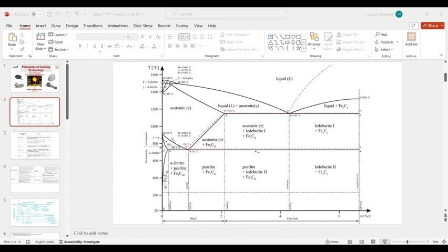So what we are going to do, we are doping some extra element into the surface of your casted material or whatever type of part you are going with. We are doping some extra material at the surface only, until some depth of around, we can say, 500 or 200 microns sometimes. Not more than that.